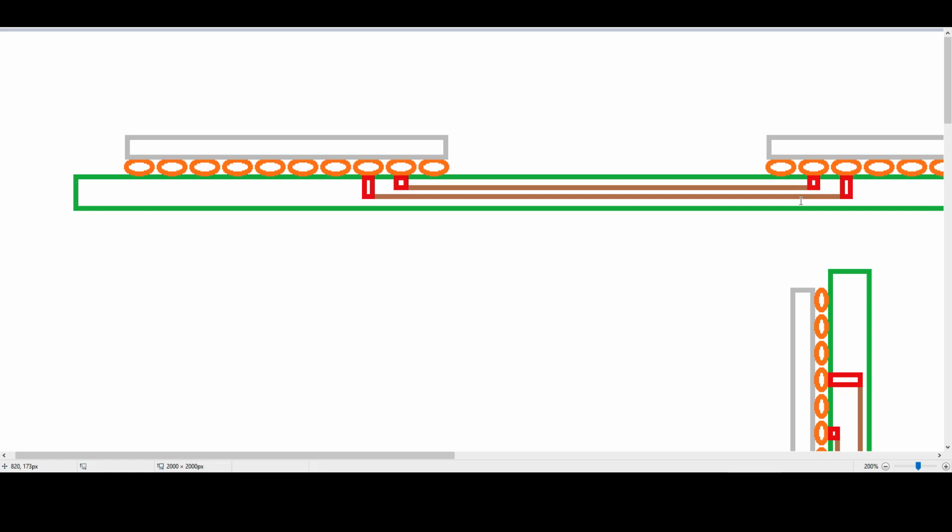Commonly also, you'll see on some motherboards that the area where the memory traces are, there's nothing there other than the memory traces themselves and everything related to the memory. And again, that's to keep that area clear of the interference that would cause damage to our signal integrity.